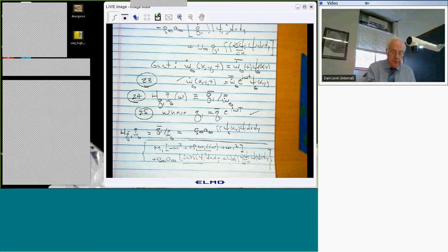What about this term? What does that do? Well, I claim this term, let's look at these terms in terms of their dependence on frequency. This is omega squared. This is an inertia term. In the piston theory, there is no aerodynamic inertia. By the way, in low-speed flow, incompressible flow, there is aerodynamic inertia in the classical model. But in piston theory, there's no aerodynamic inertia. But there is this thing. And this thing doesn't depend on frequency, which means it's like this term. What term is this? This is structural stiffness term, right? Well, some people would call this an aerodynamic stiffness term.